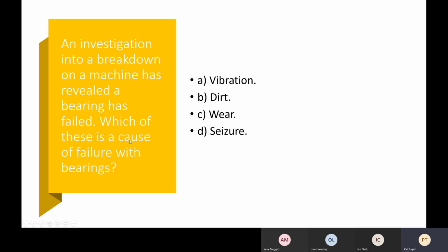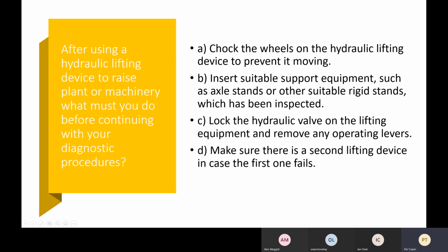Let's try another one. Let's move on. So, after using a hydraulic lifting device to raise plant and machinery, what must you do before continuing with your diagnostic procedures? B. Yeah, it's B, isn't it? Yeah. Insert suitable support equipment such as axle stands or other suitable rigid stands which have been inspected.